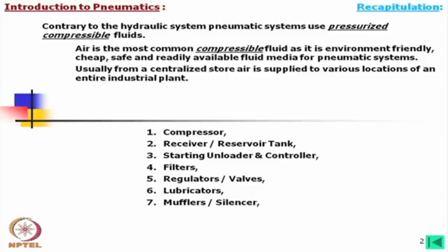When gas is released, then it is released to the atmosphere, air particularly. In that case, it makes a noise. So, essentially we need a silencer at the end, but we also need a silencer even when it is entering the system, I mean the utilization end. That silencer is usually called an online silencer.